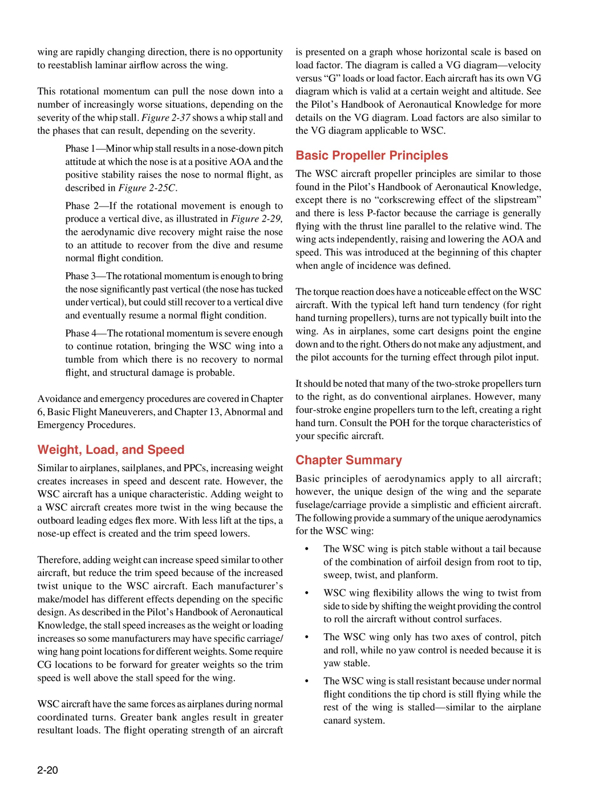The torque reaction does have a noticeable effect on the WSC aircraft. With a typical left-hand turn tendency for right-hand turning propellers, turns are not typically built into the wing. As in airplanes, some cart designs point the engine down and to the right. Others do not make any adjustment, and the pilot accounts for the turning effect through pilot input. It should be noted that many of the two-stroke propellers turn to the right, as do conventional airplanes. However, many four-stroke engine propellers turn to the left, creating a right-hand turn. Consult the POH for the torque characteristics of your specific aircraft.